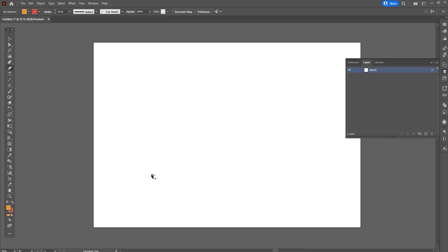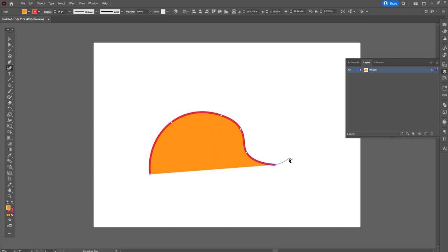To start drawing, much like with the pen tool, simply left click, select your second point, and once you left click, it's going to automatically want to make your third point something that serves as an end point between the arc and the starting point of your first 2 points. Left click again to see what I mean. So as you can see, it wants to draw a curve essentially based on the points that you give it. It'll naturally default to continuing to draw a curve that's going to continue to flow as you continue selecting points.